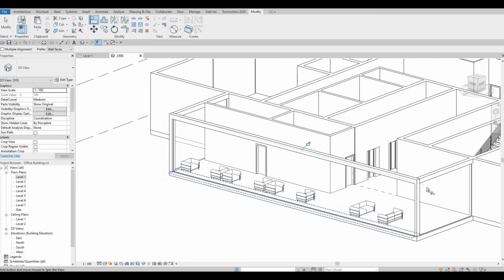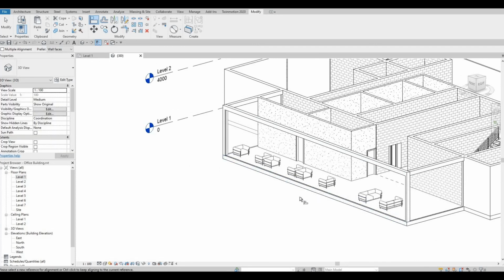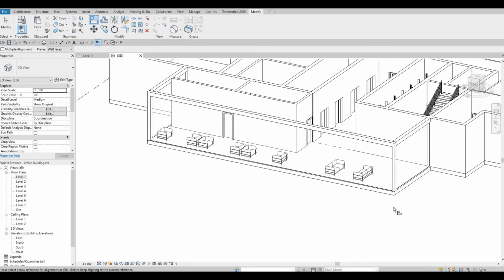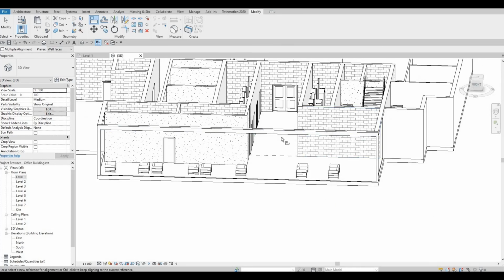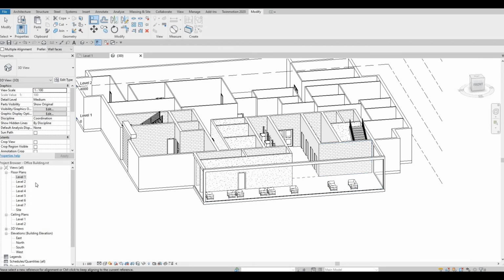So as you can see, I was able to put them all in the same level for the height. I'm going to leave it like that for now. And then what I'm planning to do is we're going to change the way the grid lines, and we're going to add in a door here, a curtain wall door, so that everything looks better. So we're gonna leave it like that.